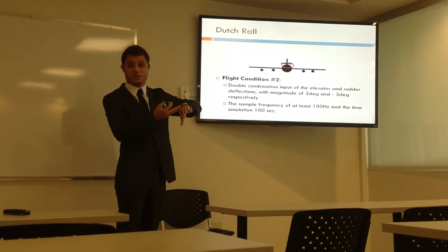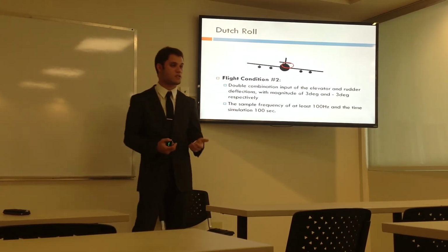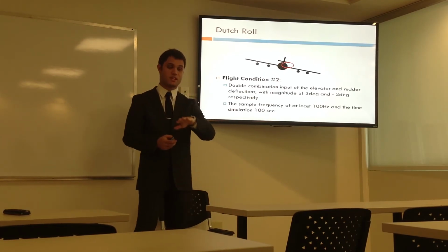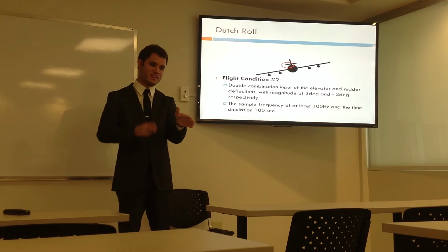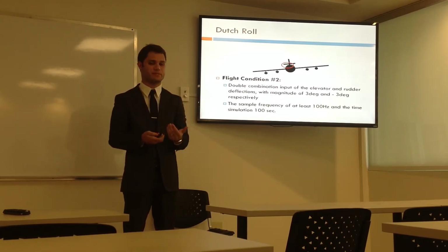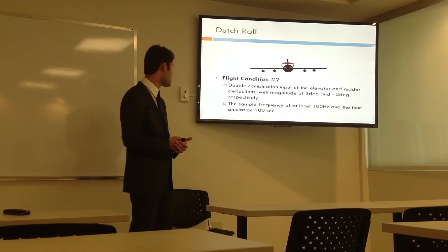And once it generates more lift, it also generates more drag, which is called induced drag. It's drag caused due to lift. Once that happens, it's going to try to stabilize out, so it turns the other way. And now this wing is generating too much lift, and it just starts oscillating again in a damped motion till it goes to its original undisturbed state.